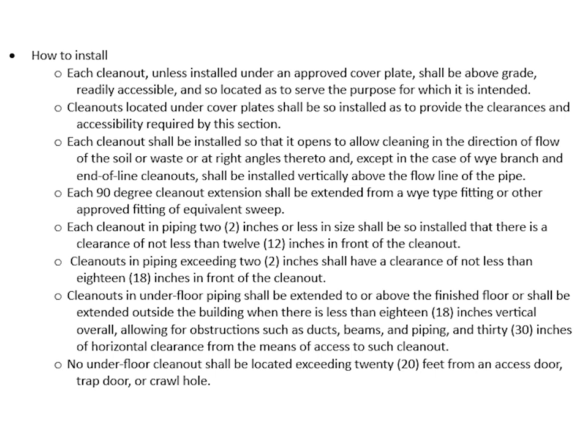Each 90-degree cleanout extension shall be extended from a Y-type fitting or other approved fitting of equivalent sweep. Each cleanout in piping 2 inches or less in size shall be so installed that there is a clearance of not less than 12 inches in front of the cleanout. Cleanouts in piping exceeding 2 inches shall have a clearance of not less than 18 inches in front of the cleanout.